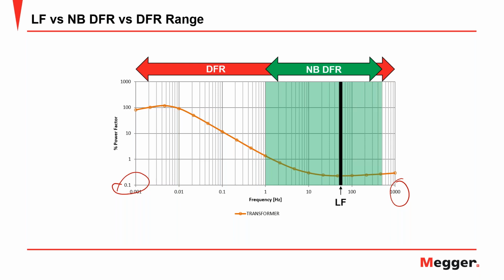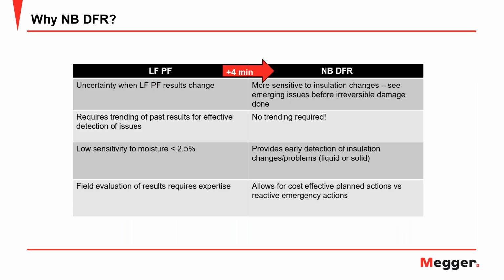So very important, very critical. And many people will ask about timing, and I have a little chart later on for you to look into this analysis. And the time is, let's say, between 3 and 4 minutes. So approximately 3 minutes that you will need to take to run this narrowband test on your bushings.